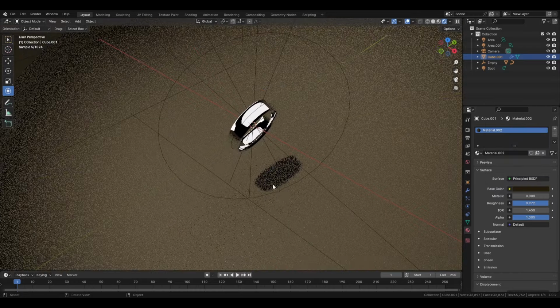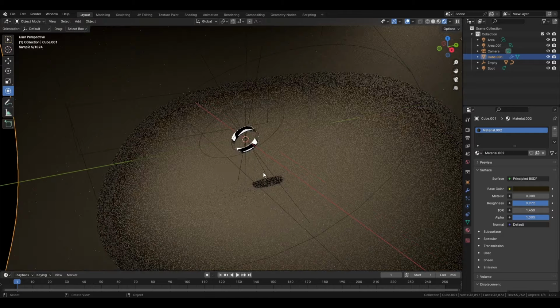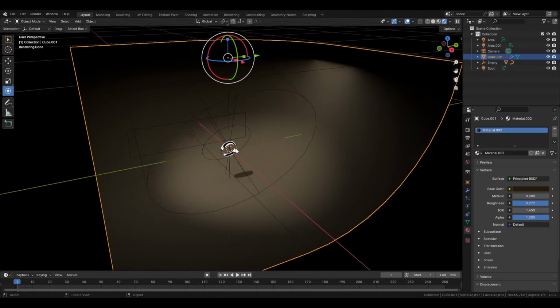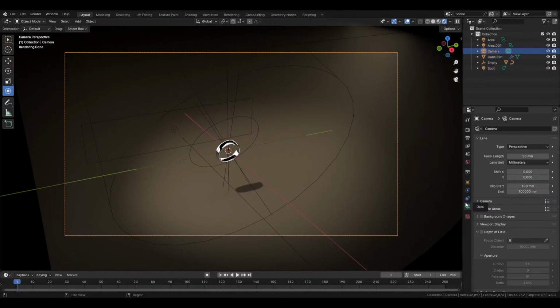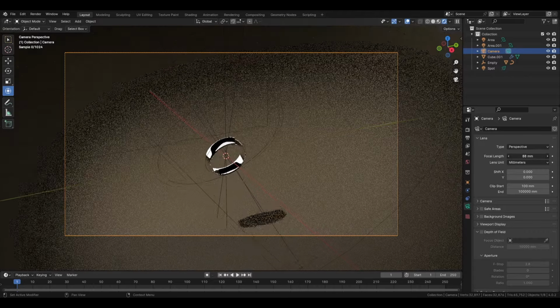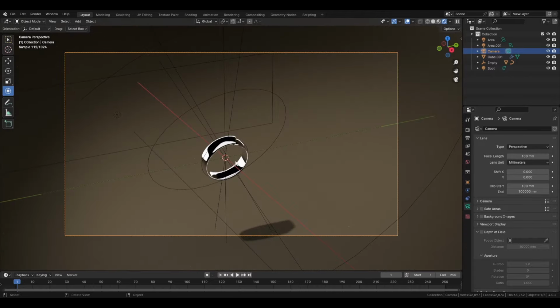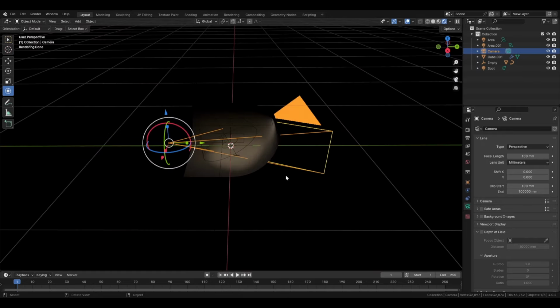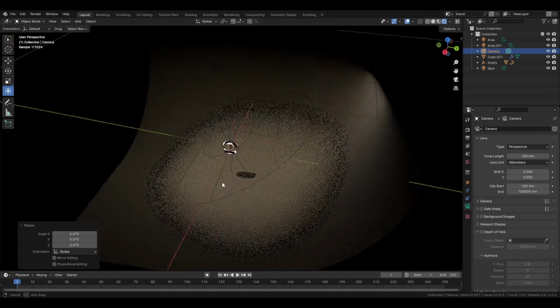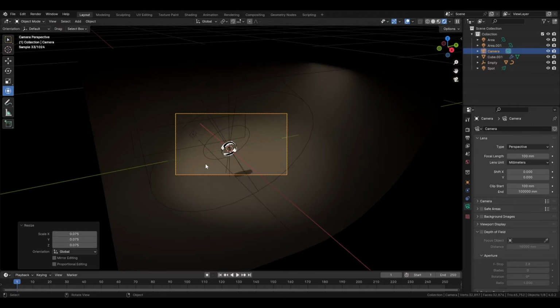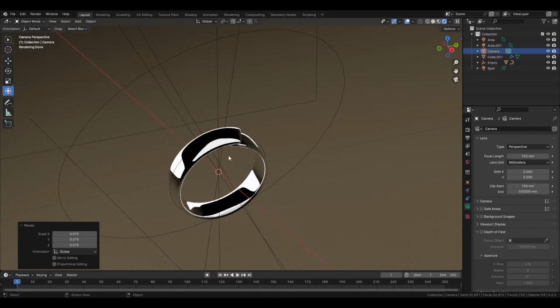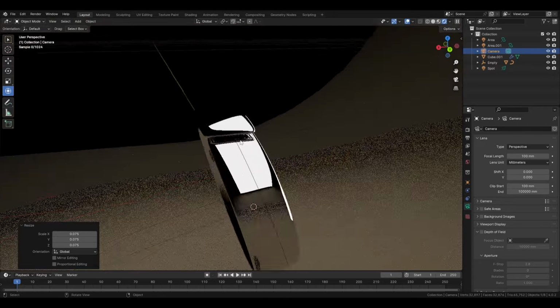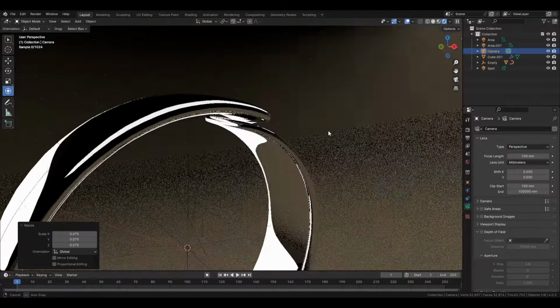And we can add a camera that is looking in this direction. So you have only one camera, so only one active camera. So you can press Control Alt 0, and it's going to put your active camera where you're looking at. And then in the camera settings, we can add a focal length a bit longer, like this. And yeah, I think that's nice, like this. Here, put it slightly smaller. And yeah, so that's already looking nice, like this.